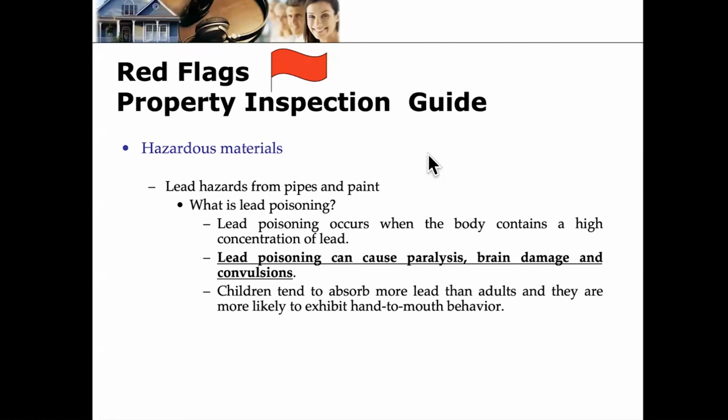So lead-based paint was certainly an issue. But after all the tests and all the study we had to do to get certified, it turns out they said if they paint over it, they conceal it, and it's no longer a danger. So the lead paint issue became almost a moot point if someone painted the property. But if they started sanding things down and remodeling, lead dust got in the air, and that began to create a problem. So if you have a house built in those time periods, make sure you let your client know the age of the house. It could have lead paint, or may have.